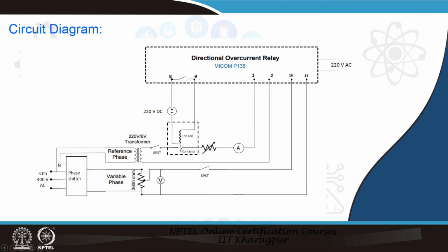When the angle is within the setting in the forward direction, the relay goes for a trip decision, and when it trips, the current path is interrupted, as mentioned earlier in the overcurrent relay. So, the circuit breaker opens and isolates the network where the current is high.